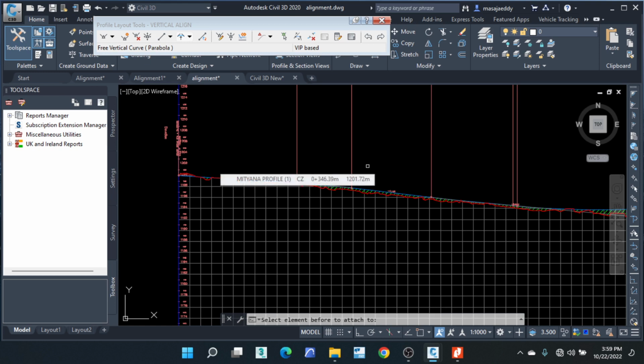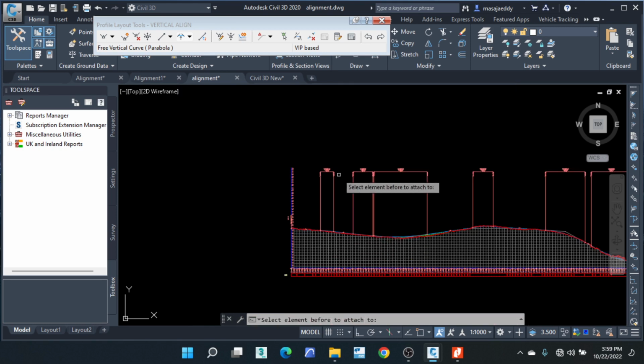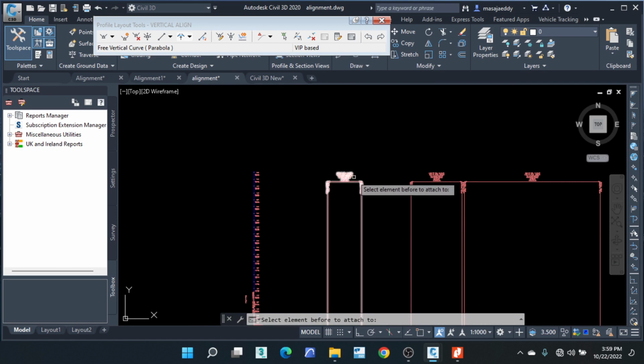If it's a horizontal curve, they provide road signage for the sharp curve, the chevron signs, both on the inside and outside of the curve, and also the speed signs. Then also inside, the road humps. So that is why we look at all these parameters while we're doing a vertical profile.